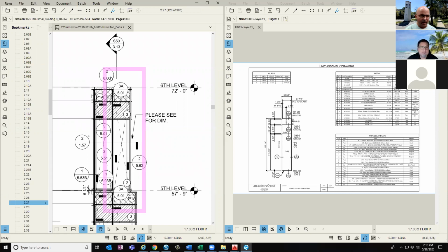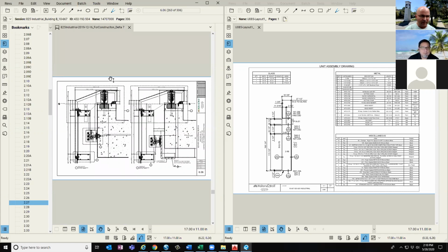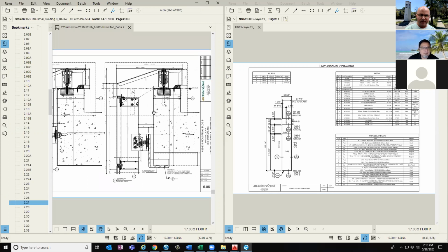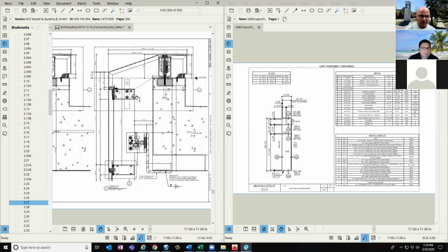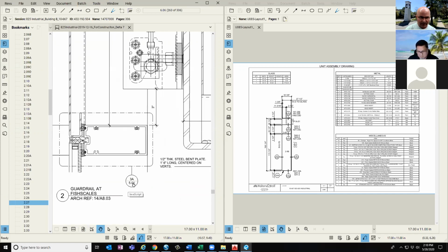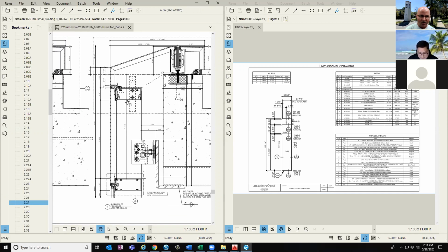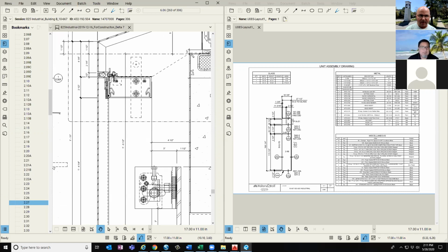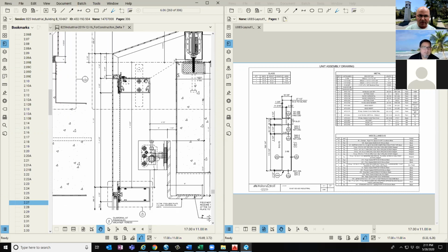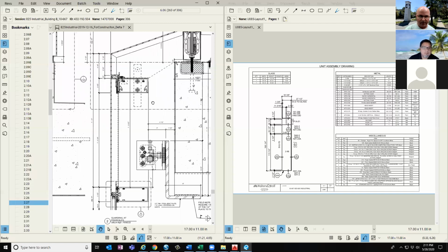Then when I go to my upper detail, the 2 on 606, okay, so this one's going to make me pay attention here. I've got a lot of things happening. So I'm seeing that this is the horizontal I saw in that other detail. It's called out here as my 3A on 501. It's showing that I've got a panel attached here. It's showing what's happening with the top of my unit. This I would consider to be a parapet head because it's not using a stack joint head member. And I've got a bayonet that's going to be used for lifting that unit for hoisting.